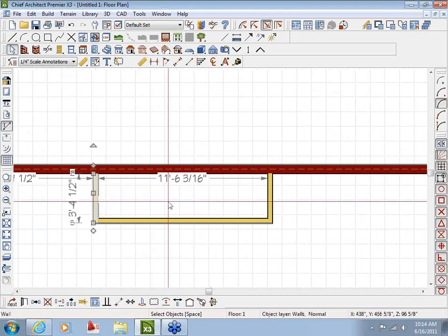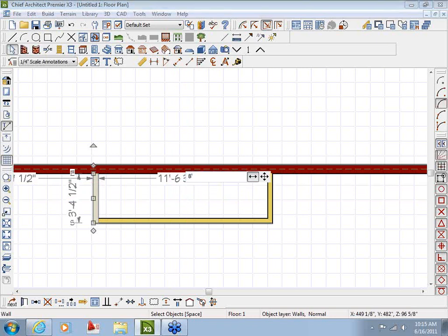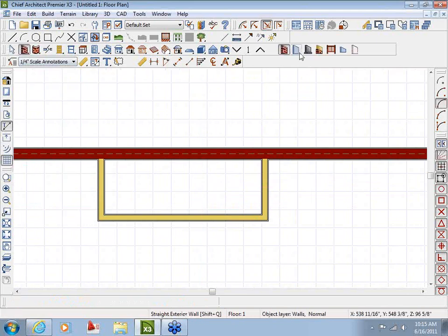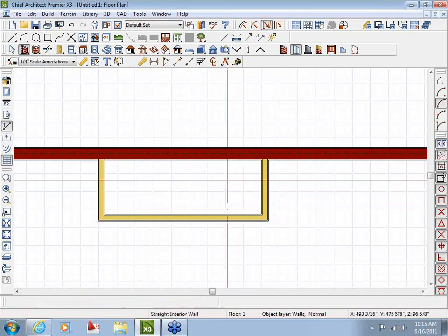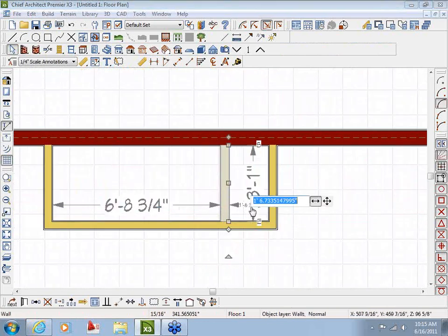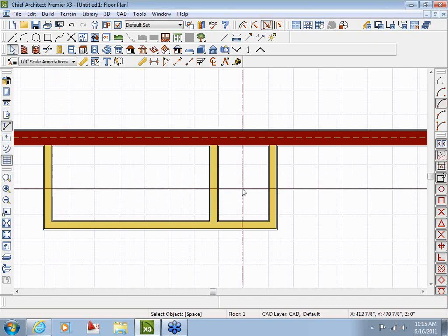And for those of you who still use, or in the states that use the 8 1/4, 9 stair rule, we need a minimum opening of 8'8" for headroom clearance. Now we could have a closet here, and it wouldn't be an angled wall. We could have a closet here, but this would have to be a raised floor. Okay, so we still need 8'8".